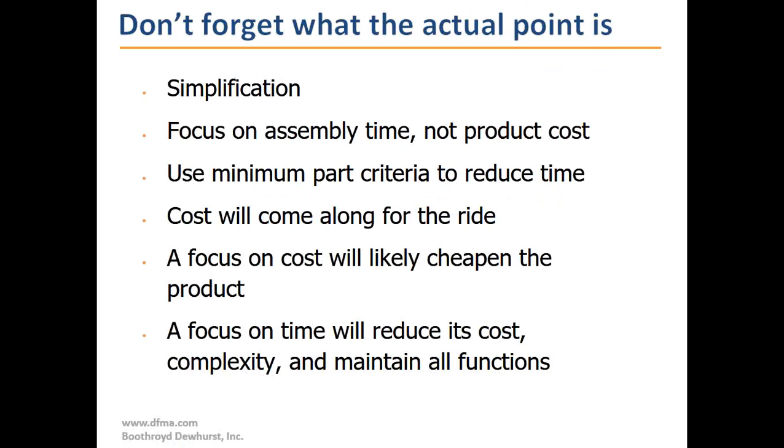But his point was that while we go on and on talking about how assembly time really isn't important because it's never a significant portion of the cost of a product, it is the thing that you should focus on if you want to do Design for Assembly and accomplish great things. Because what we've seen is that if you focus on cost, which is the natural focus, you end up doing, in a lot of cases, nothing more than cheapening your product. Well, if you're able to focus your efforts on assembly time reduction, then it leads you to a better result in that you are able to reduce the cost that comes along for the ride while you focus on the assembly labor time. But at the same time, you maintain all of the functionality.